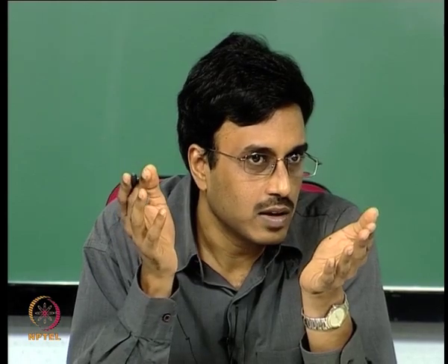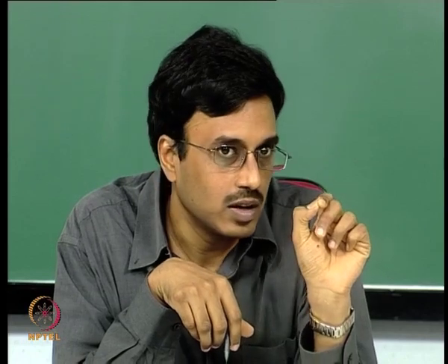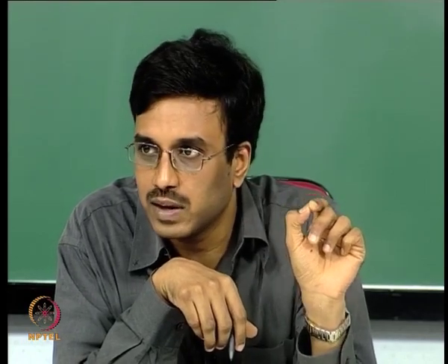At every stage, not only must these two sequences be m minus 1 bits, but I also make sure that the sum of V1 and V2 is the same as V. Then finally, when you add all the thermometer sequences T1 through T of n minus 1, that by construction will be the same as V. Does this make sense?